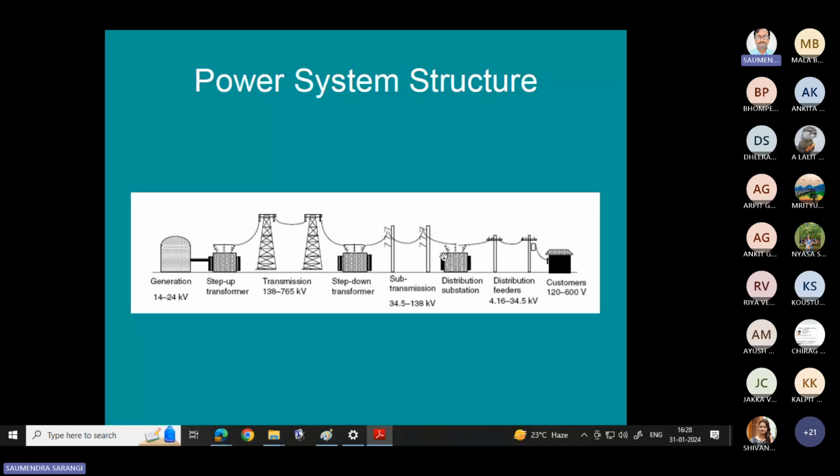So when the equipment needs to be very safe and we are protecting with a ground, when the fault occurs because of the insulation breakdown, the current will be really high. During that point, we need to break the circuit, whatever the faulty element is. In those cases, we have two things: one is called a relay and the second is called a breaker. The time period for which the current is flowing should be very small. Otherwise, if you allow a longer time period, it will definitely burn everything.